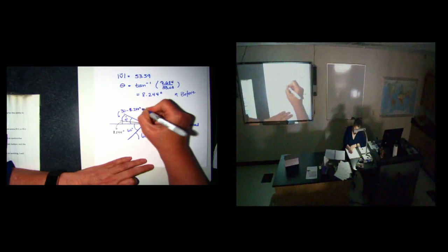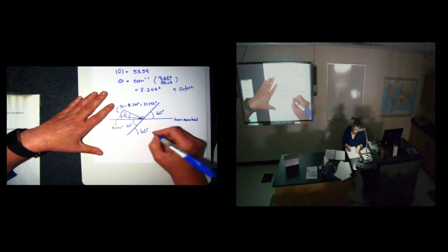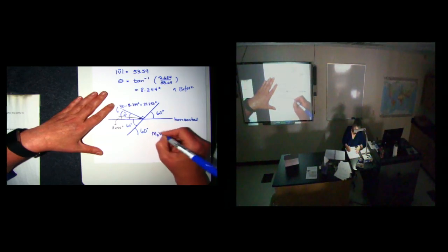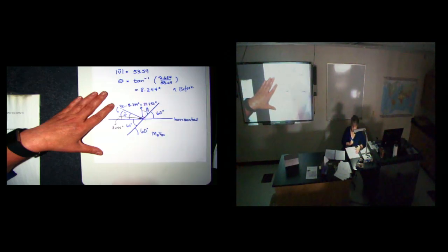Sine of 21.756 degrees. And then you get VB sine of the angle is equal to 24.885. So now I can figure out the tangent of the angle, because I'm going to do my sine over the cosine. It's going to give me that the angle is 51.4 degrees. I can go back and solve for VB, and it becomes 31.8 feet per second.